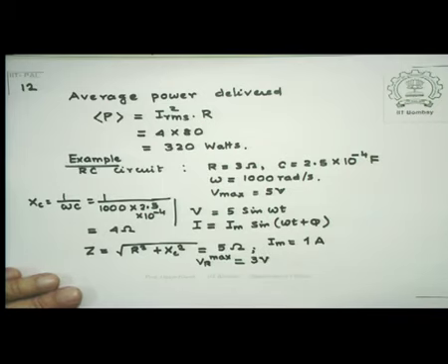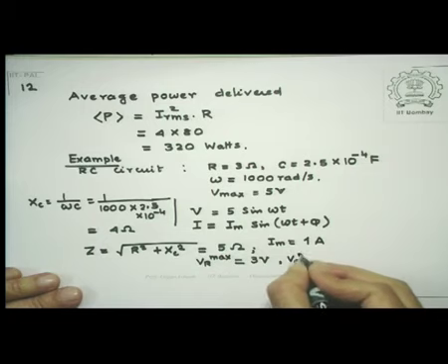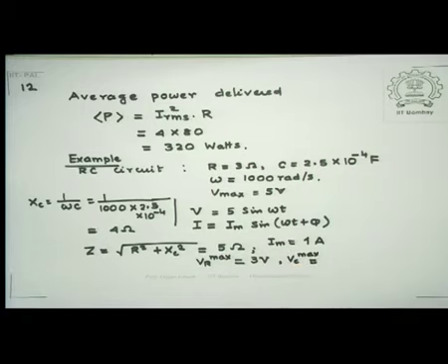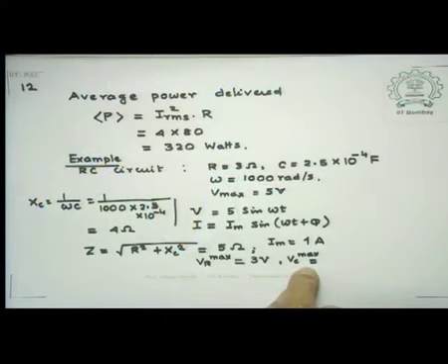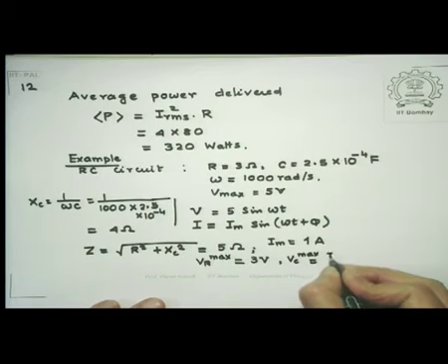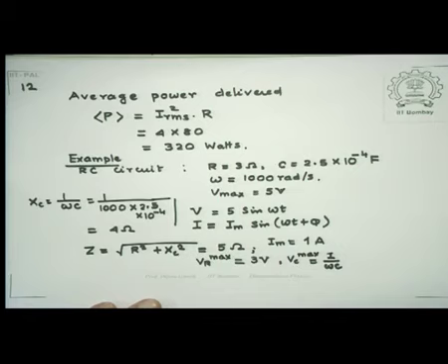What is the VC max? Now this is where you must remember, I am not adding. In series resistance circuits, the drops simply add, but I am not adding it, and that would be given by I divided by omega C, IXC. So this is 1 over omega C was 4, so 4 into 1, so that's equal to 4 volts.